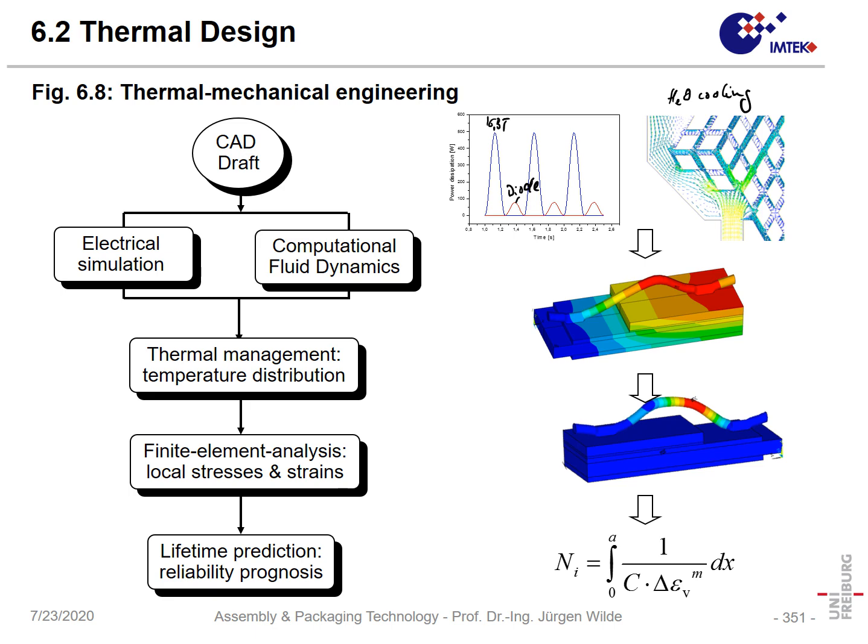And in order to estimate the dissipated heat in a precise way, we can use CFD, which is computational fluid dynamics. In that way, we get data, and if we unite both data and also take together the solid state behavior of that device, we get the thermal management and we get the temperature distribution.